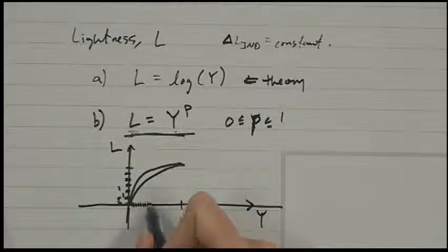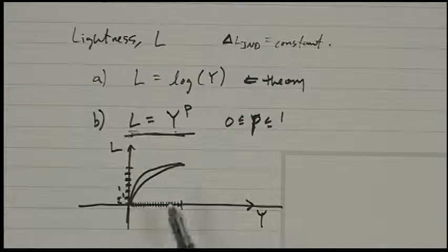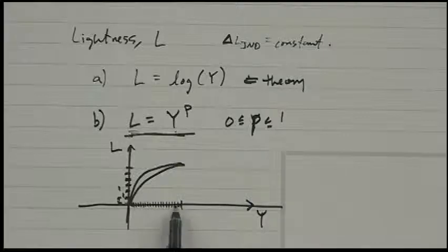So we'd have to use a really small step size all throughout here, and that would be very inefficient, because all these step sizes up here in the high luminance levels, we can't perceive them anyway. So there's no reason we have to allocate bits to encode all these different steps up here.